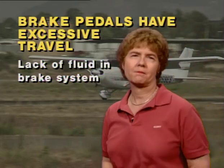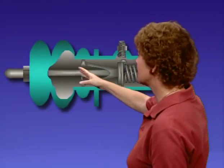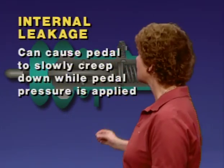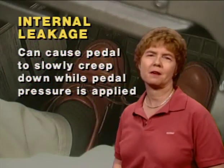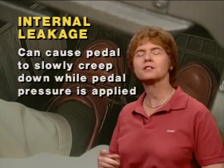Now, with the brake master cylinder unit, if you get internal leakage in that unit, one of the things it can cause is the pedal to slowly creep down while the pedal pressure is applied. That is not the same as fading brakes. Fading brakes are the result of overheating the brakes and glazing them.